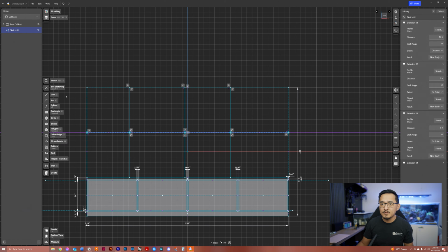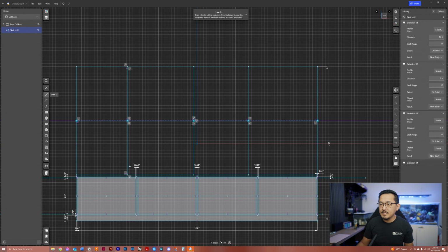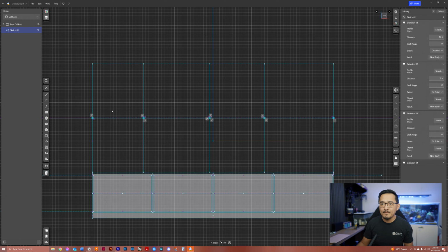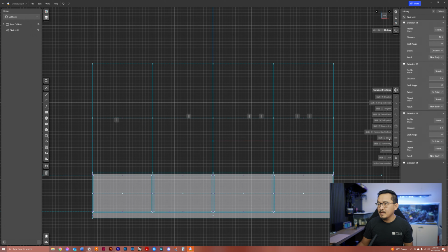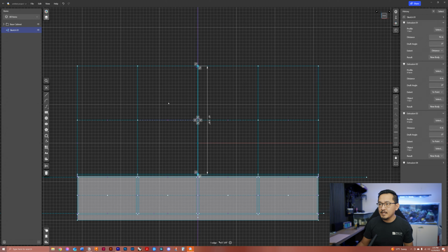I actually also need to draw my exterior panel line. There we go. And if these dimensions get in the way, we can simply close them off for now. So I have my interior construction lines here. I'm going to select equal, and it's going to equally divide up the upper partitions. Since the middle section is actually a large TV and I don't need this middle line, I'm just going to make construction for that middle line as well.